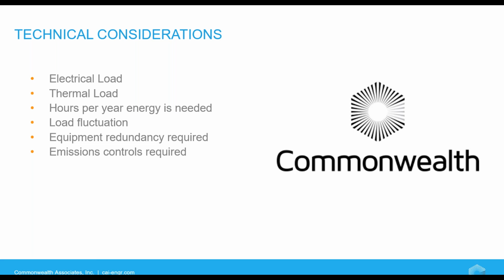Next would be how much energy is needed and for how long. Is this going to be a base load, or is it going to be a peaker that helps baseline existing energy sources? Typically, CHP systems are designed to meet the facility's year-round base load thermal demand. Knowing this will help determine which technology works the best for your application.